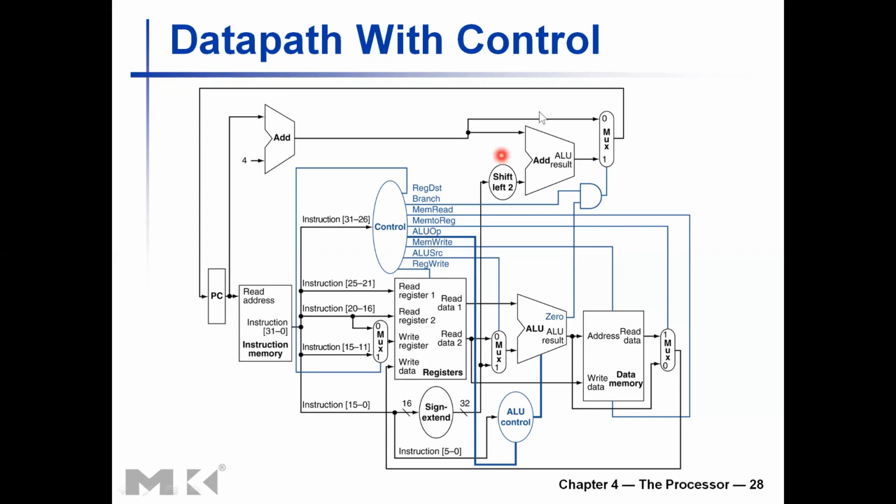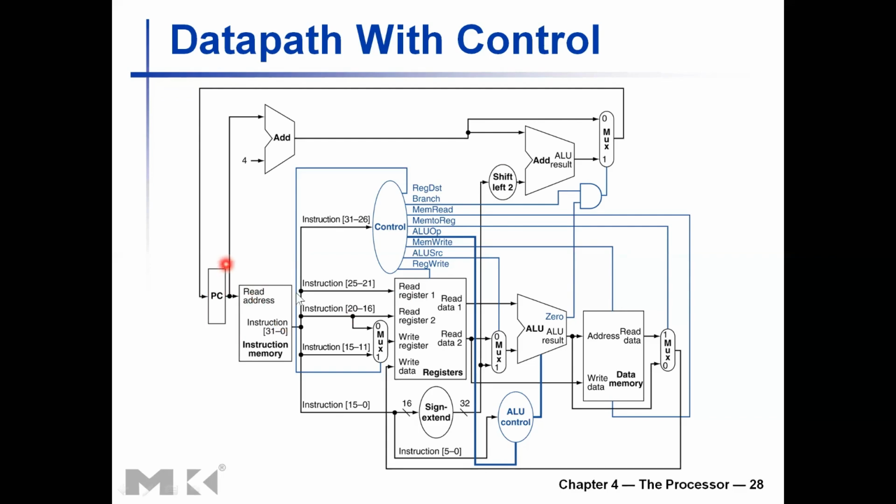for the given instructions, for the instructions that we were discussing: R type, load word, store word, and branch if equal instructions. So we had the instruction fetch elements here from the instruction memory using the program counter, and then you decode the instruction. The control unit derives all the necessary control signals, and you access the register file in order to read any register operands that are required, or you take the immediate value given in the instruction and do sign extension on it, and then go to the ALU to perform any arithmetic or logical operations that are required.